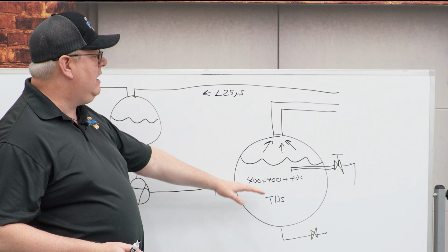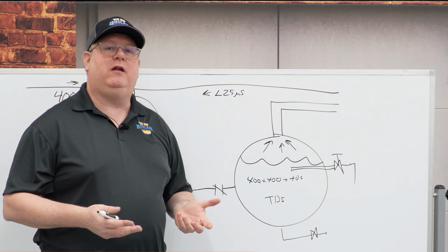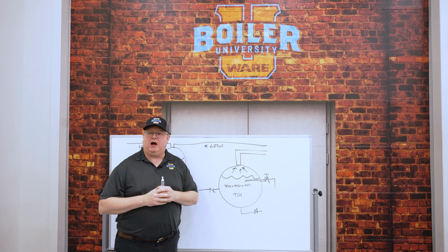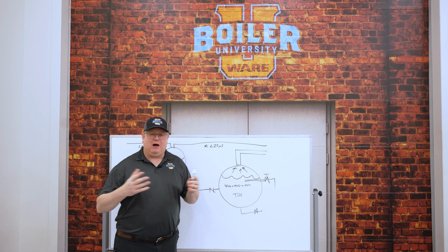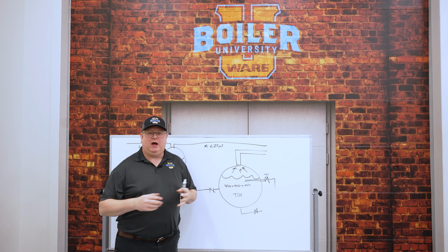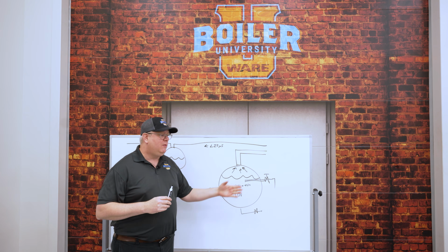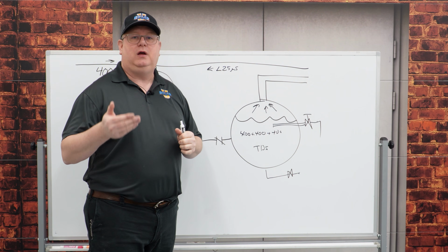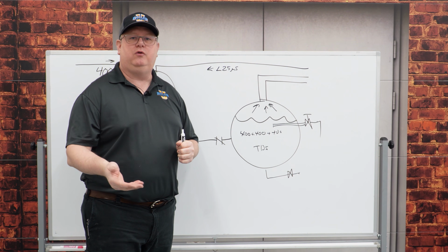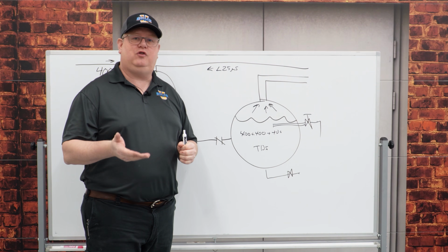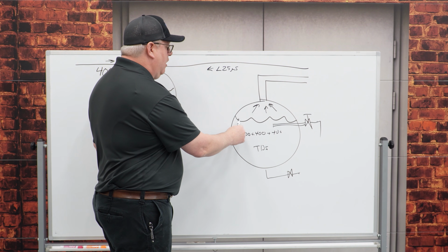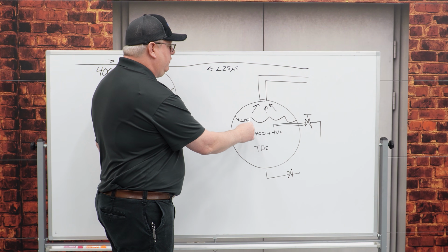And basically, any boiler, based on its design, has sort of a limit to where we want to run the conductivity. I'd love to use that water forever and not waste any of that energy, but the fact of the matter is we'll start having issues with the water level, and we can start having issues with corrosion if the conductivity is too high. Essentially, high conductivity causes foam on the water surface.